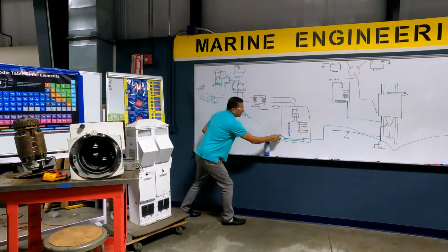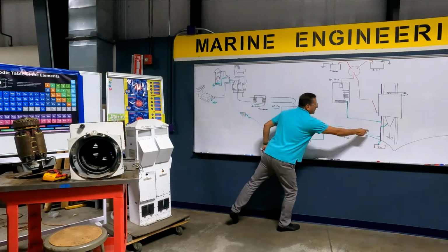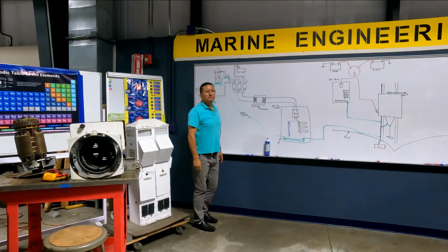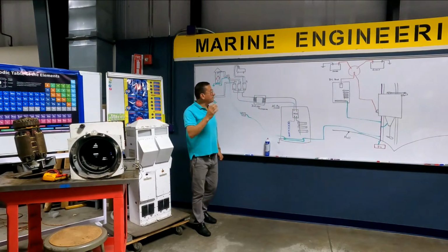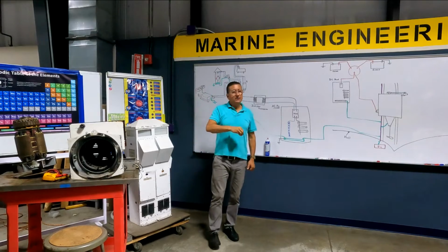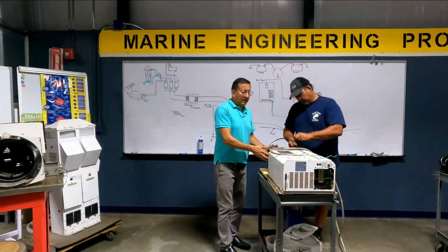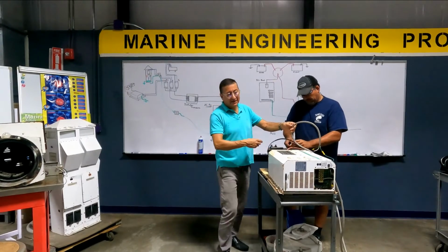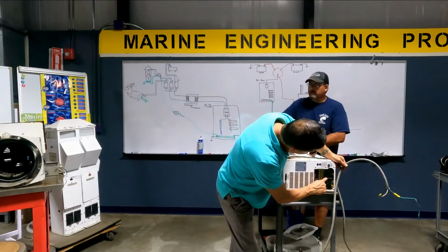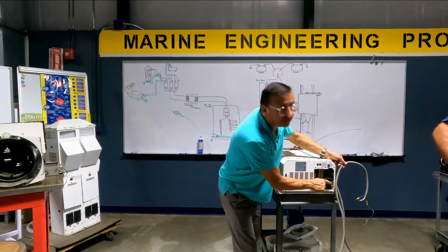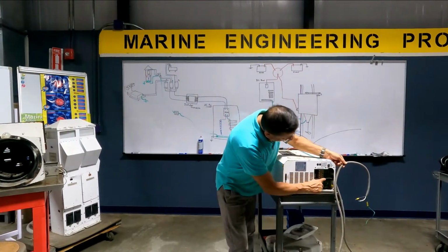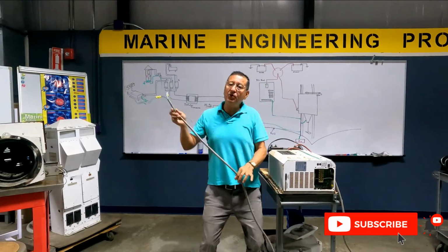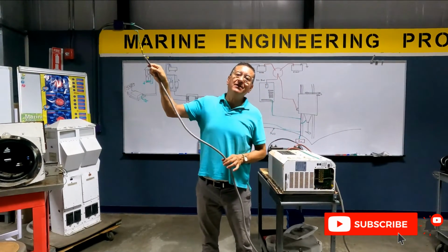This is the ground, it enters here, and the ground is connected with the bonding conductor, and the bonding conductor finishes into the sink. One thing that I need you to keep clear from today for the rest of the line. All right, look, on one side of the inverter, DC enters. And on the other side, you have hot, neutral, and ground. You see? Hot, neutral, and ground, and this is the hot, neutral, and ground that you introduce in the AC panel.